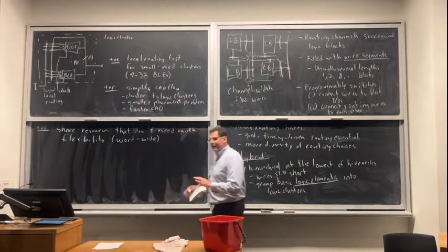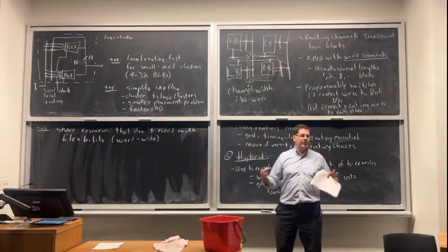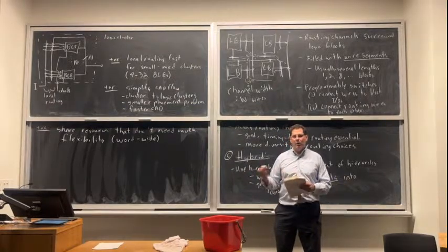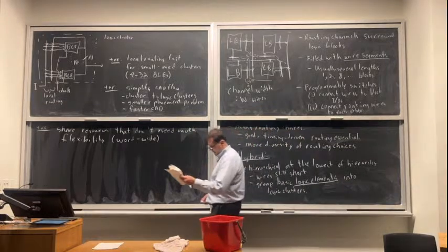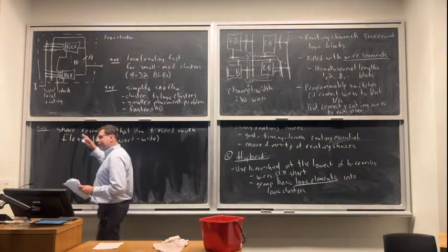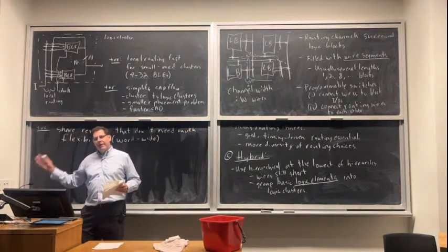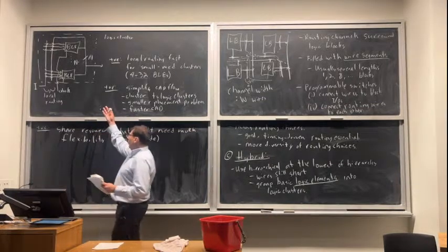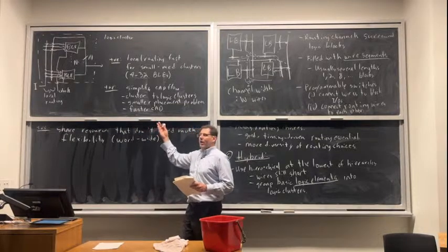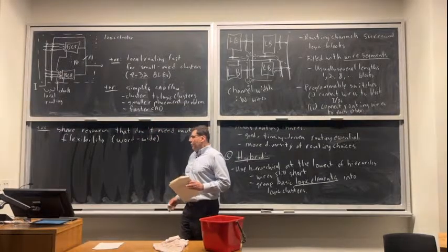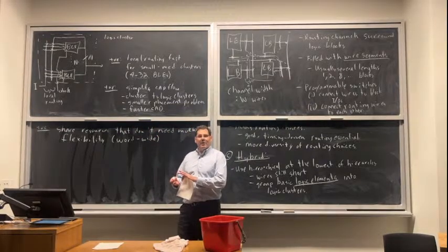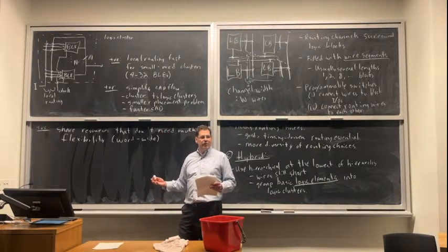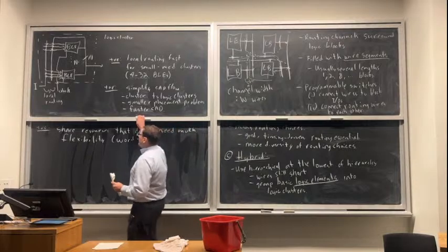Okay, so the inputs to a lookup table, you tend to have to control all of them. You don't know what logic function you're doing. You don't know what signals you're ANDing or ORing or XORing. There's all sorts of different things that happen. But clocks tend to have fan-outs of tens, hundreds of thousands of registers. So to say all of these registers in this logic block, which should have been put together by the CAD tool because they have something in common, share the same clock is not much of a restriction. And it saves a fair amount of area.